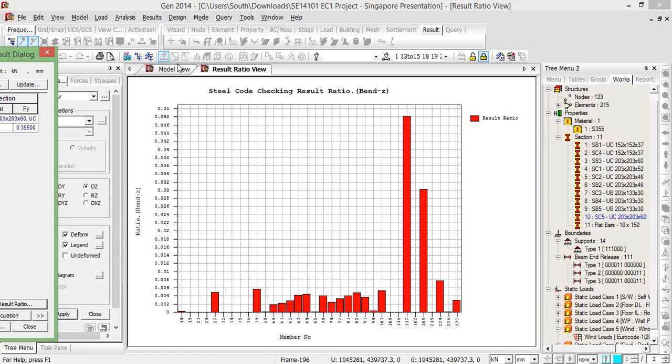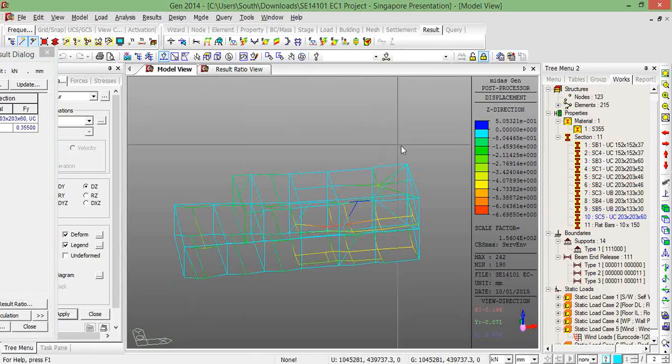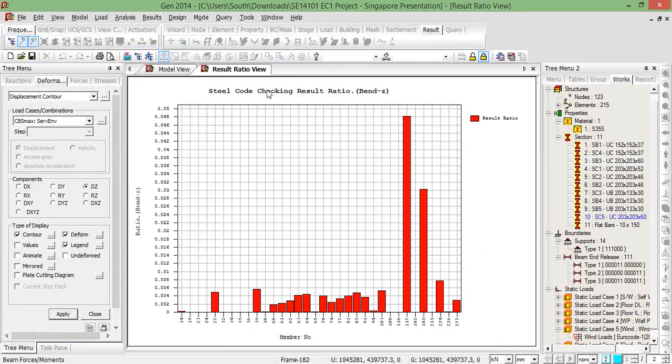In this case, because we were quite squeezed for head height and space, we had to stick with the same section sizes, and for ease of installing and making the construction phase a bit more simple, we didn't change the section size for that particular member. However, in another scheme, you could easily, for that beam, choose to put in a different section, and then you can probably arrange to have the rest of these beams being used as a slightly lighter section. We found that tool very useful.